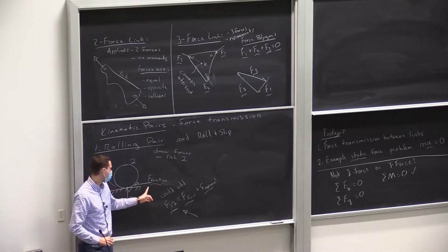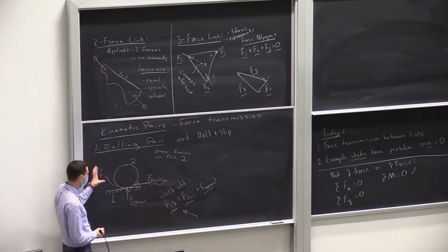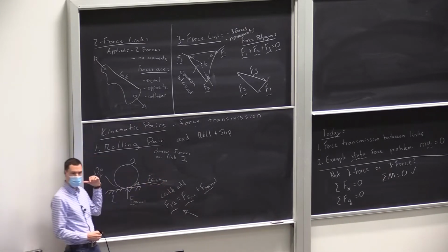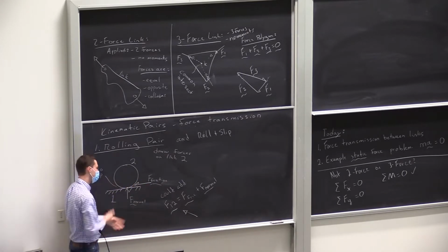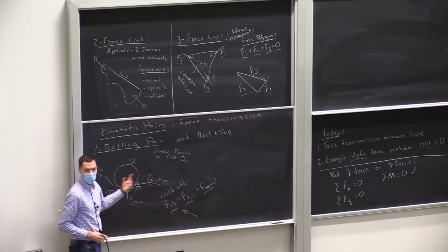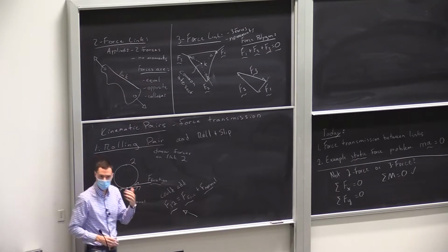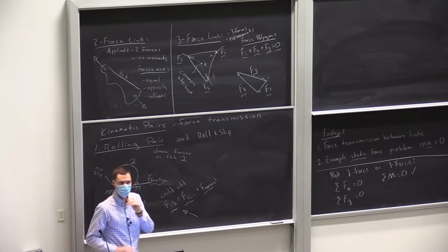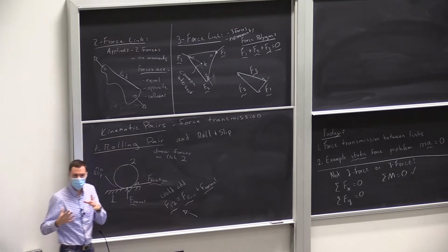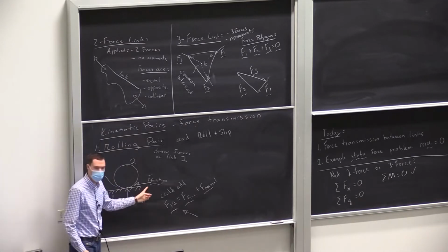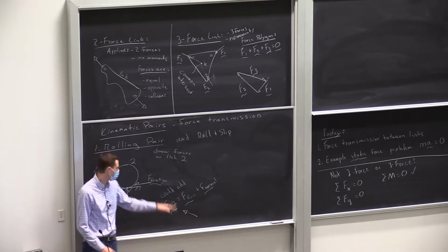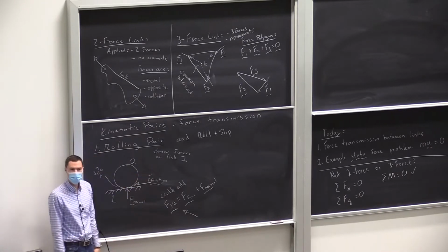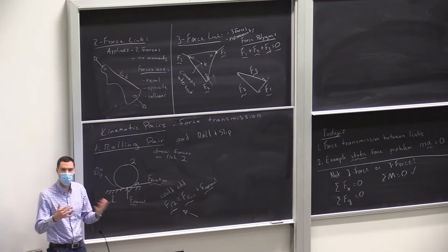They could turn out to be negative. So if this thing is sliding to the right, the friction force will oppose it. So that's the friction force if it's sliding to the right. If it was sliding to the left, this would come out to be a negative number. And we're going to solve a problem at the end of today, and we'll look at negative forces or negative moments and how we can interpret those and communicate those clearly. So when you're doing a diagram, oftentimes you just have to guess. We know the direction. We just put it on there. That's a definition, and we can use it. And they can be positive or negative.